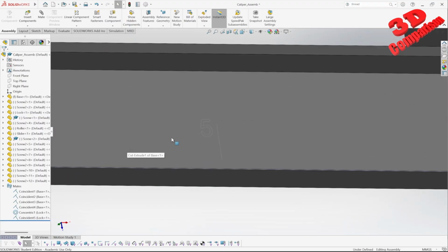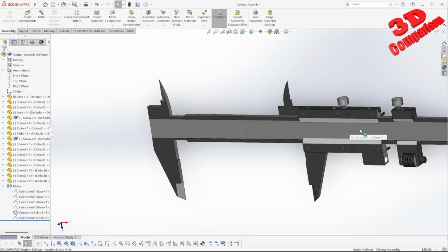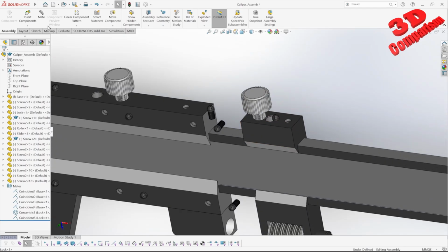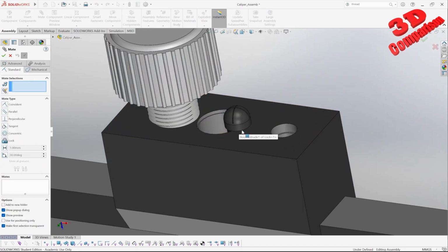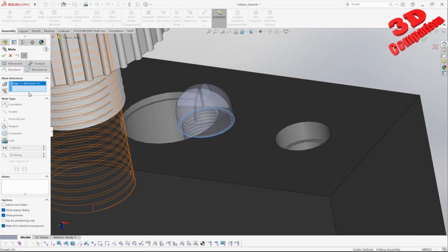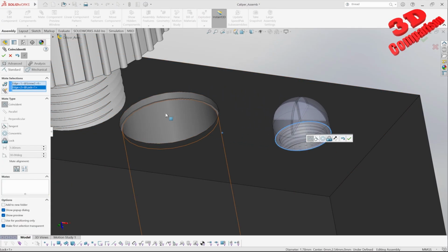We see over here that I also added that numbering, so this will be where we're going to have on that caliper that measure for 5. So let's go ahead and mate the screws. So I want that, which will be an edge. In this case, the edge that will define the bottom of that circle, even though it's misleading because a circle doesn't actually have an edge, but within CAD, we see that it has. And I will mate that over here.